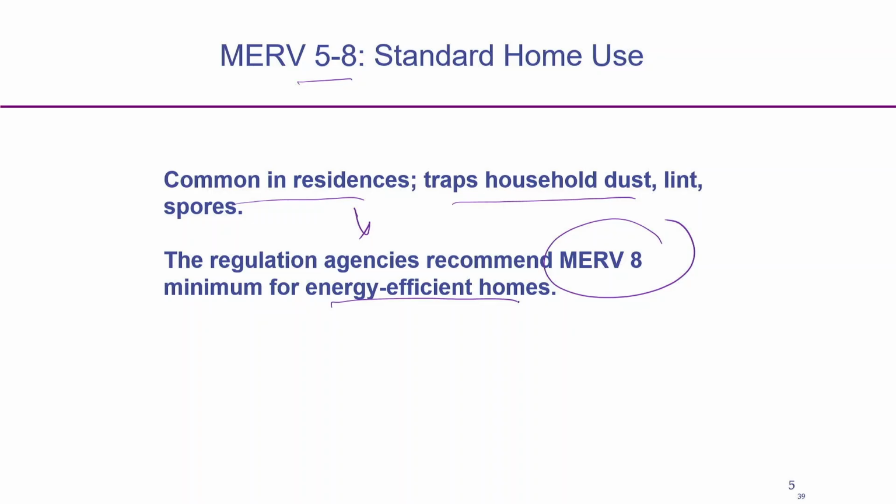MERV 8 they recommend, because it will capture the finer dust, and at the same time the pressure drop is not too high. So, the home will be energy efficient, and energy consumption will be on the lower side.